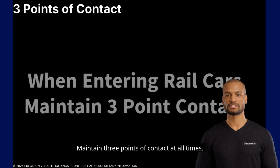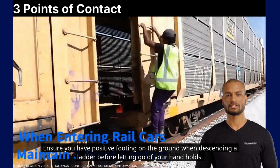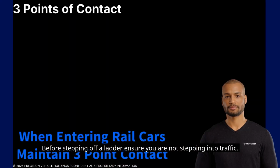Maintain 3 points of contact at all times: 1 hand and 2 feet, or 2 hands and 1 foot. Ensure you have positive footing on the ground when descending a ladder before letting go of your handholds. Before stepping off a ladder, ensure you are not stepping into traffic.